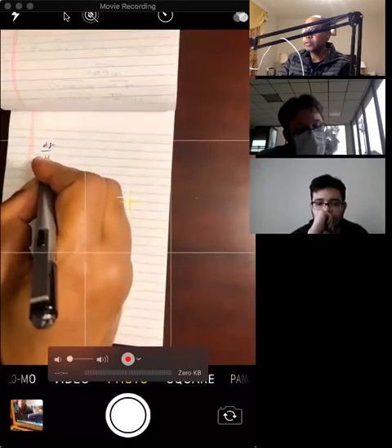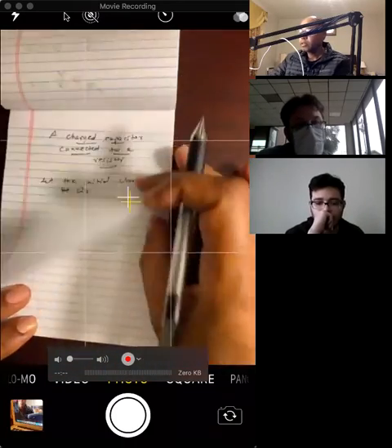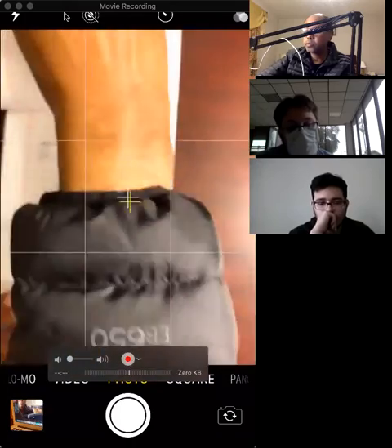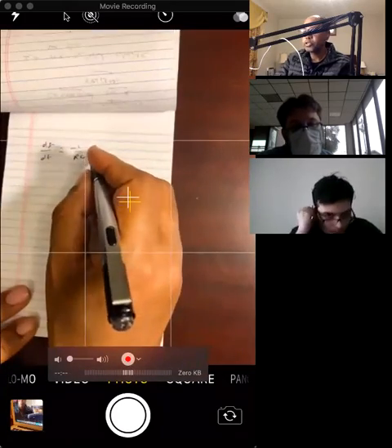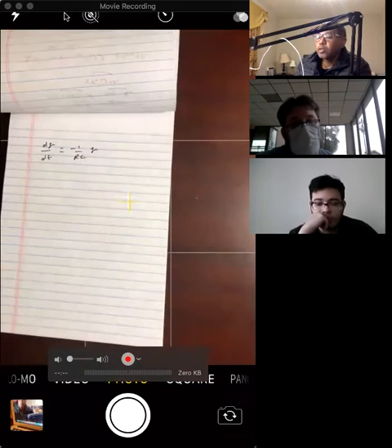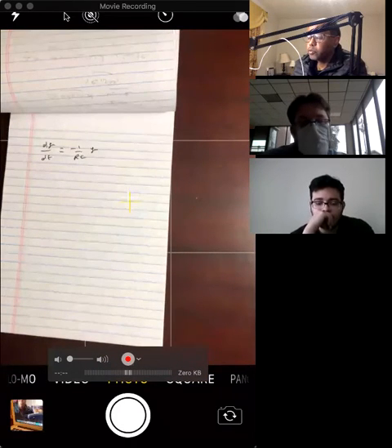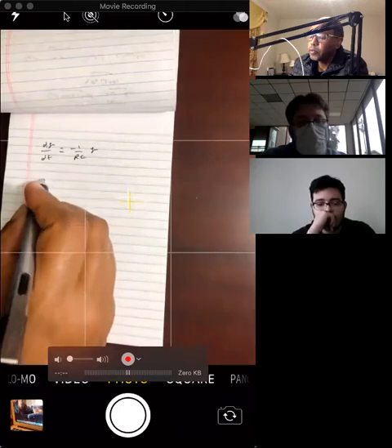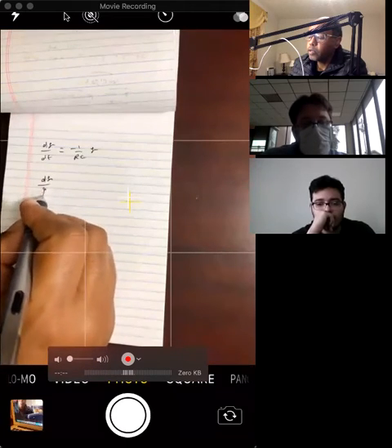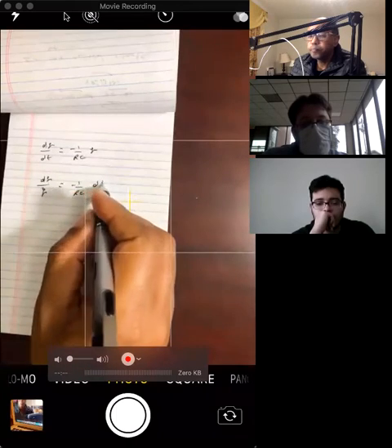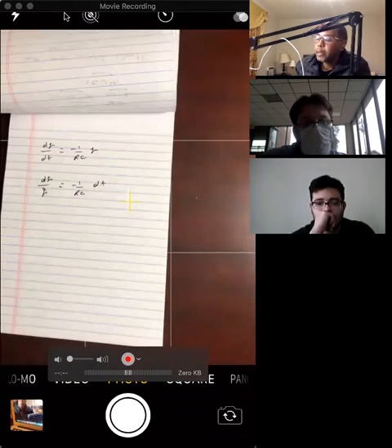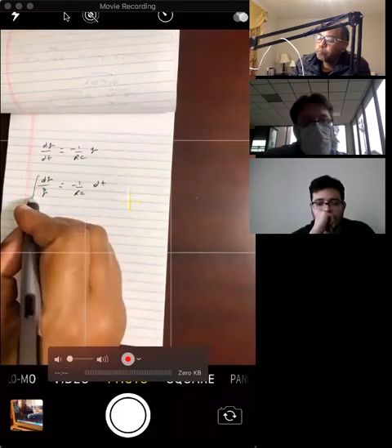dq/dt equals negative 1 over RC times Q. Again, this is a differential equation. The first thing we should do is separation of variables. In this case, we can separate them very easily. So dq over q equals negative 1 over RC dt. Okay, so let's integrate.